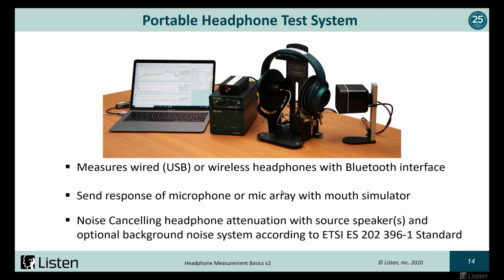And if we want to measure the microphone in the headphone or headset, a lot of times now the more expensive headphones even have a mic array or microphones for active noise canceling. We need some sort of artificial mouth or loudspeaker if we want to measure that. And if we really want to get a little more sophisticated, we want to test the noise cancellation on the headphones with various background noises.